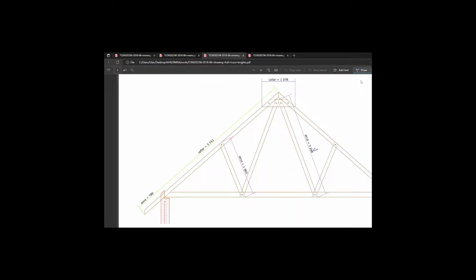This says scaled, and it's 5.74. Let's take a look. So 5.74 is the same, right, as the full truss. I would not risk saying it's the same every time, but in this case it is the same. It's the same scale dimension, so it's the same. It's scaled. There are 10. You just applied. Now the trick here, obviously, is a half truss, not a full truss. So in the full truss, what we did was we said one raft is this length. There are 2 in a full truss, and there are 34 full trusses, right?